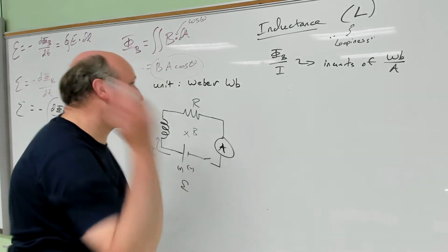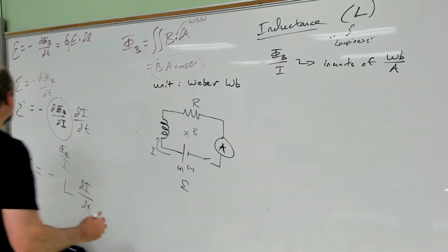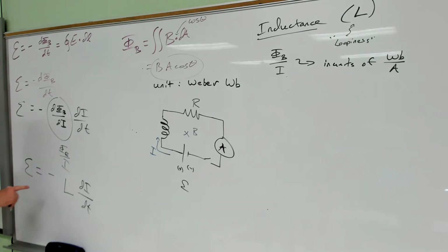And so instead, what people oftentimes will use for inductance is they'll take this equation and they'll rearrange it. So let's see L, let's put the di/dt under here. So EMF over di/dt, this is just for figuring out the units. EMF over di/dt, you see, hey, that's just volts over amps per second.